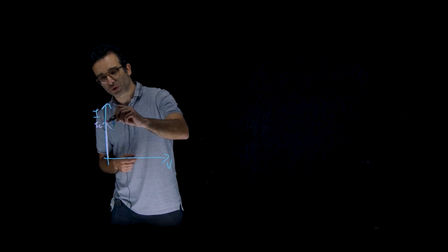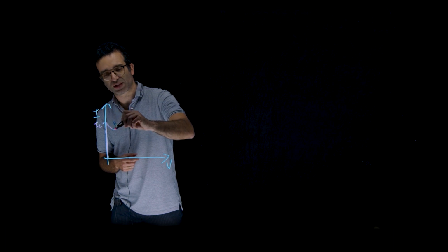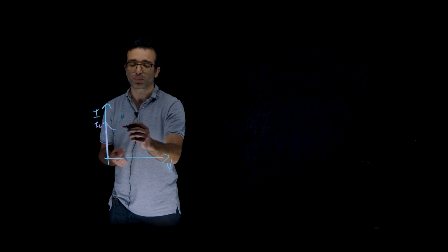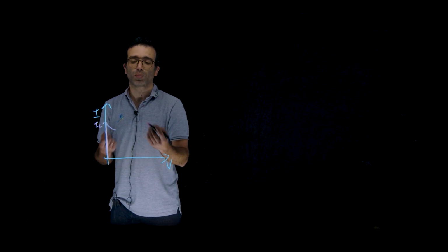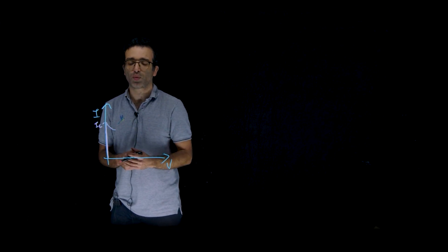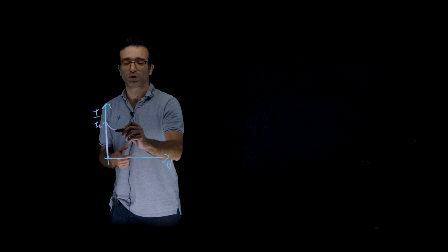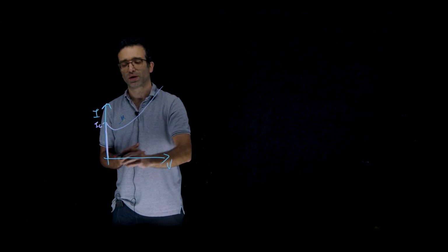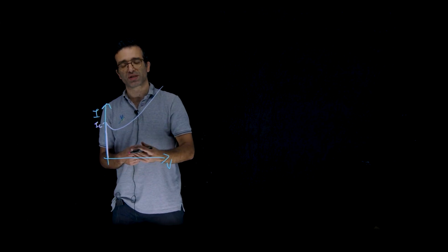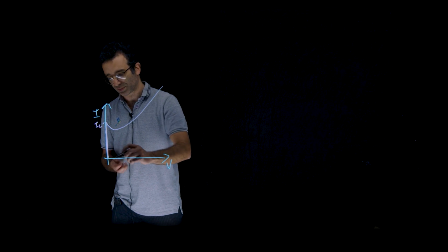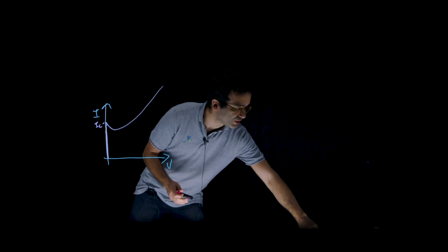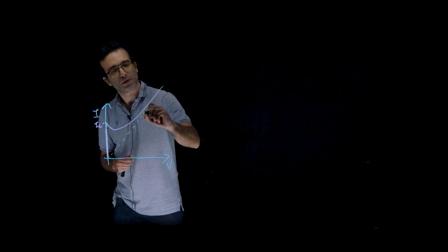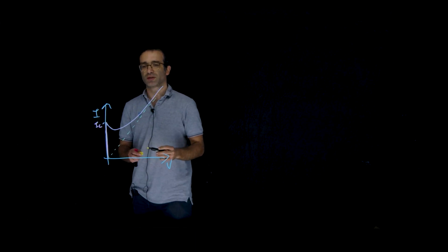So then there is a negative differential resistance, and if I continue to raise the voltage, at some point the normal ohmic conductance will start to dominate, and then I will reach some sort of a linear slope, which corresponds to the normal state resistance of the device. And in principle, this should cross zero, as Ohm's law prescribes here, okay, at least in this way.